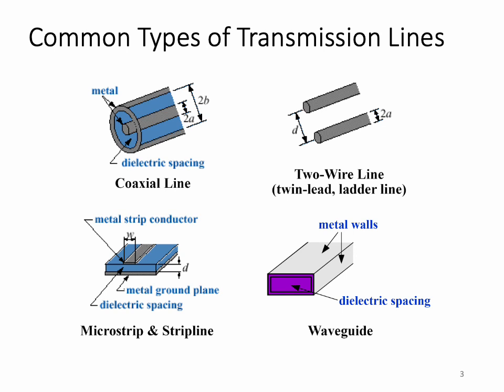Today, there are many types of transmission lines, ranging from coaxial structures, or coax, to parallel lines, such as twin lead or ladder line, to printed circuit board microstrip and strip line, to waveguides. In the first three examples, transmission occurs along a metallic conductor which is supported by dielectric material, whereas with waveguide, transmission occurs within a hollow metal tube in which the metal walls provide distributed inductance and the empty space between the walls provides distributed capacitance.